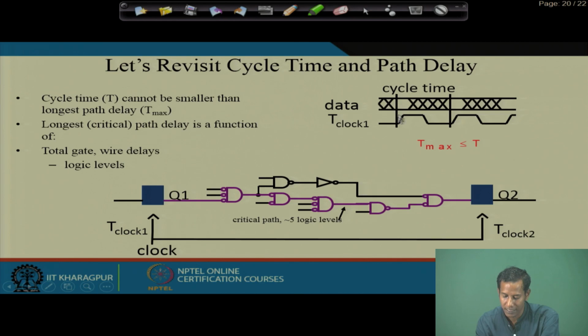So, say these are two flip flops, connected with some combinational logic in between. To avoid violations, we always have to consider that at the clock edge the data must be stable, it will not change its value. So, here you see at every clock edge, the data are fixed, it is not changing its value.